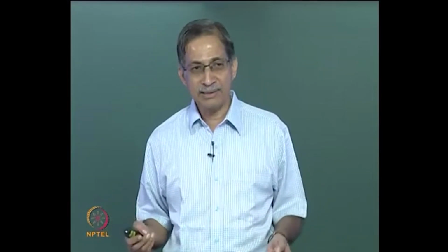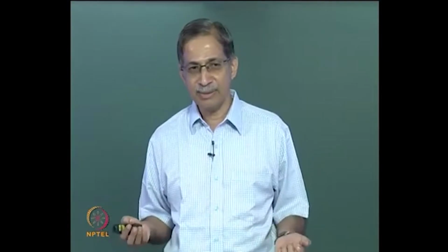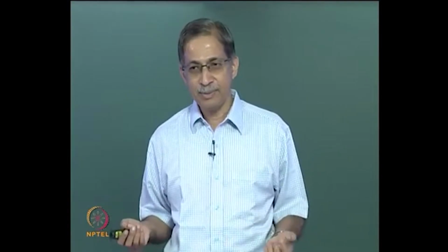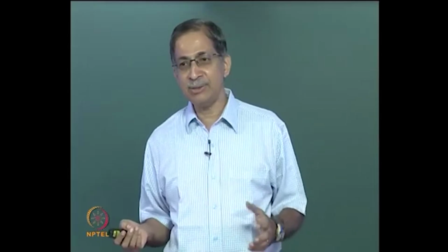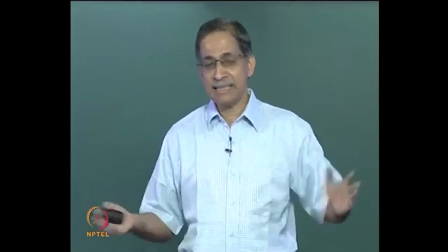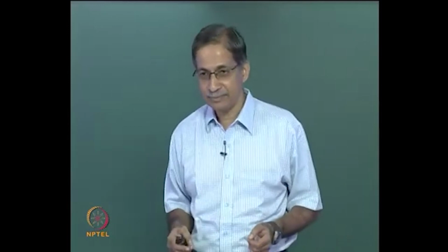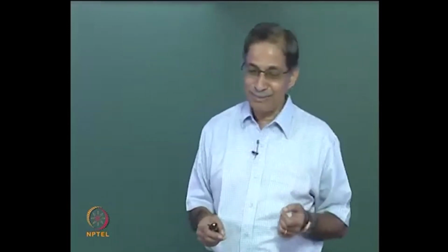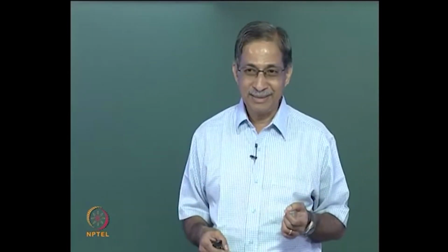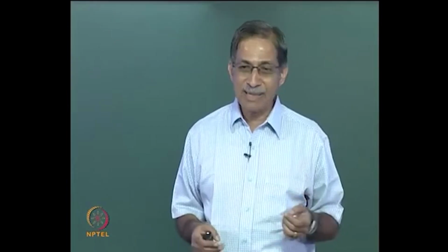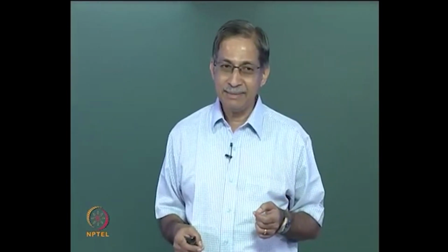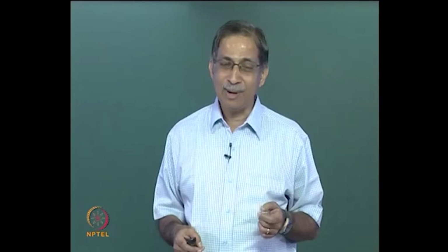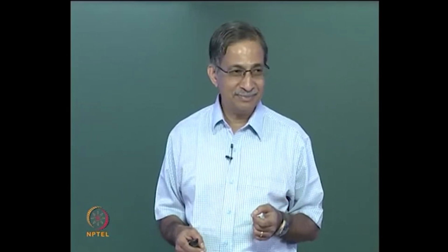What do you do next in this conventional stiffness method which we studied? You have to convert these to the global axis system. How do you do that? What is the transformation matrix you will use? TF. Will you use Ti? Will you pre-multiply by Ti? Not Ti, then what? TF.